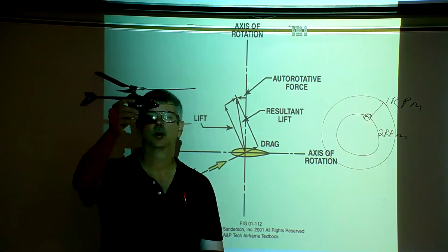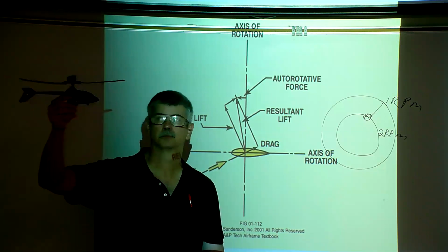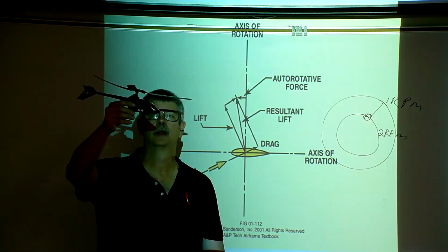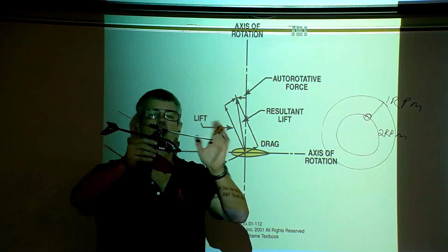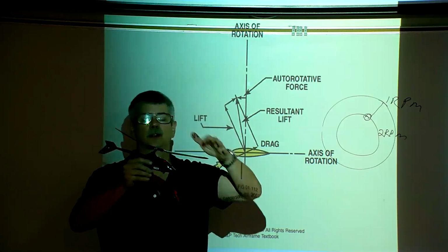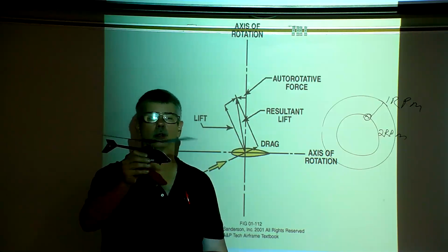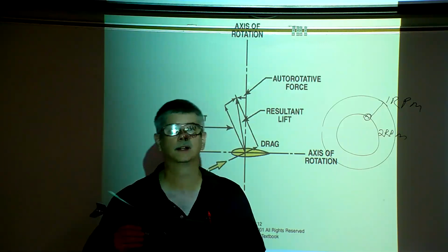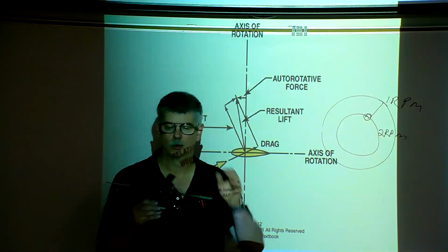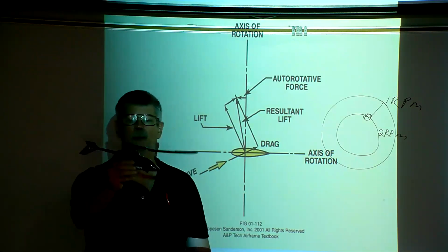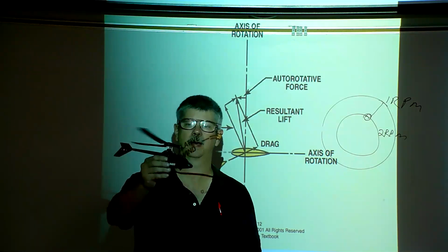Okay. So if we have a power outage, the pilot would kind of pitch the nose down. And as that happens, the air flowing over the rotor blades creates enough lift forward to keep the rotor blade spinning. Now, the pilot usually will move the collective down, which lowers the pitch of all the blades to gain as much momentum in the rotor blades as possible.